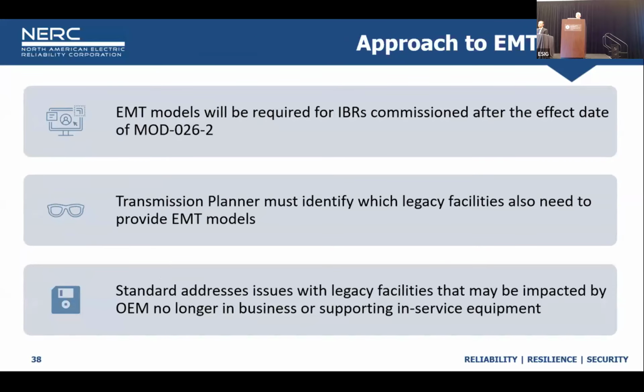Okay, next highlighted topic is our approach to EMT models. A lot of the transmission planners on our team were emphatic about including EMT models in this standard. One of the reasons is that they're saying you can't accurately determine ride-through performance of an IBR without having the EMT model. So the way the standard is trying to address that is that any facility that's commissioned after the effective date of the standard would need to provide an EMT model.